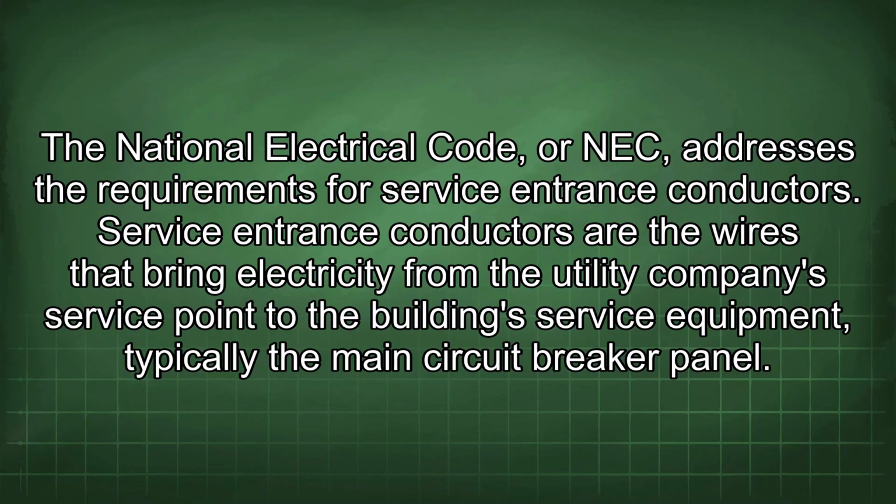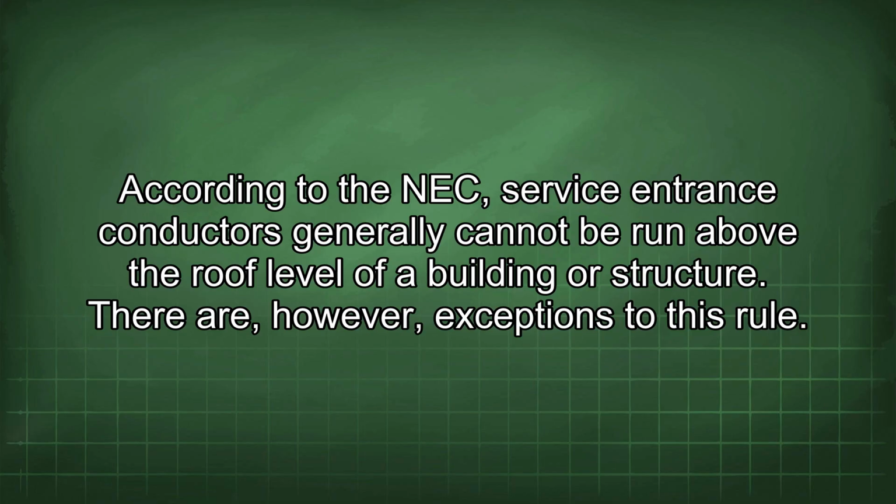The National Electrical Code, or NEC, addresses the requirements for service entrance conductors. Service entrance conductors are the wires that bring electricity from the utility company's service point to the building's service equipment, typically the main circuit breaker panel. According to the NEC, service entrance conductors generally cannot be run above the roof level of a building or structure. There are, however, exceptions to this rule.